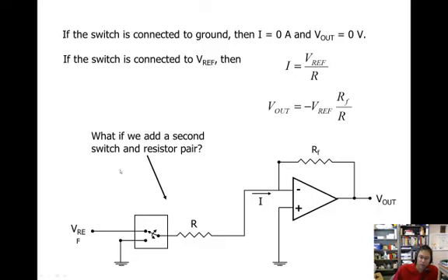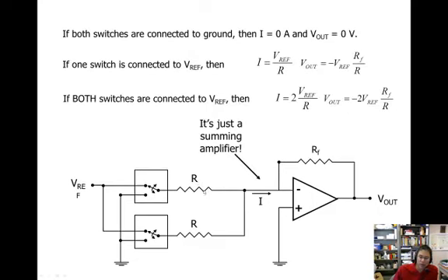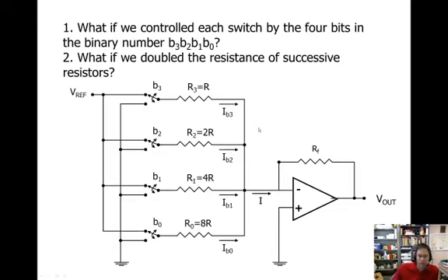And if we can add more voltage references with more resistors here, so now this is going to be a summing amplifier, because now it's these two resistors in parallel here, and there's one on the bottom. So it's going to flip up to the top here. So now it's twice that. We can continue this process here, but let's be a little bit intelligent here. So here we're showing 4 resistors, but we're going to grow them, right?